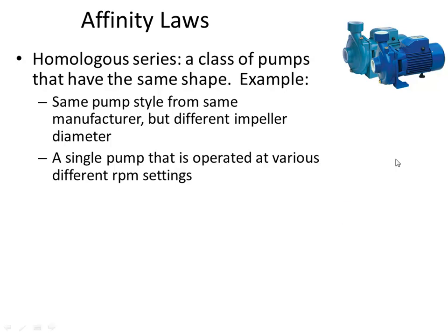You can see the two pumps that are shown here have a similar shape. It's just that the pump in the background has a larger diameter of the outlet than the pump in the foreground. And there are these mathematical relationships that equate how switching out a certain pump and replacing it with another pump is going to affect the pump head that can be generated, the rotation rate that's needed, and these affinity laws can also be used to tell you what the performance will be if you replace a single pump with two pumps.